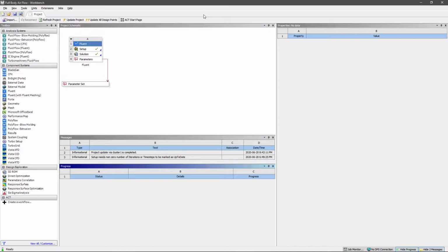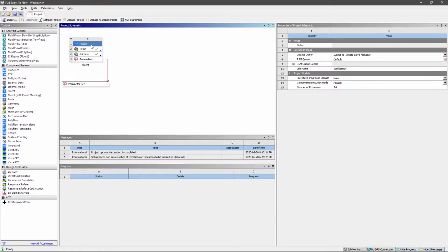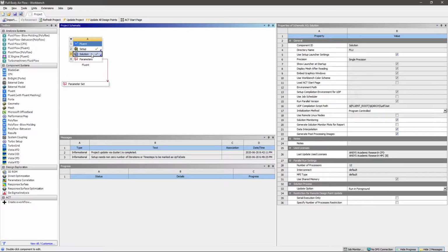So let's get started by importing the CFD-Post module. I say import, but it's really not that complicated. First off, you'll want to open a workbench instance with your Fluent module. These will be the solutions that you've generated for whichever CFD simulation you've just run. You'll notice that they have completed by the fact that there's a check mark there.